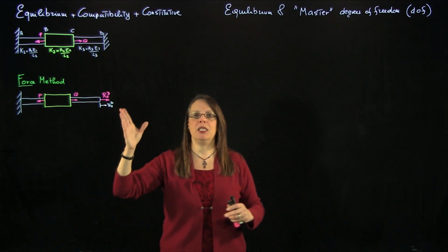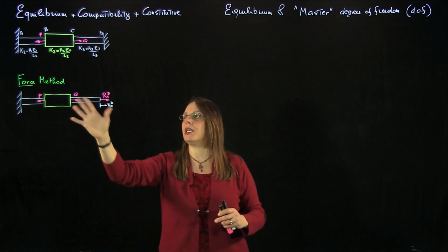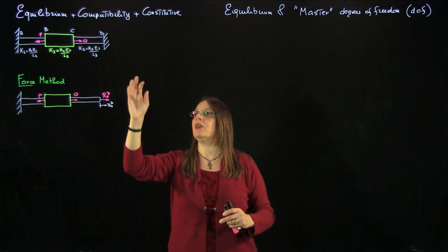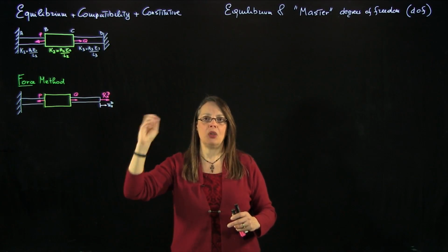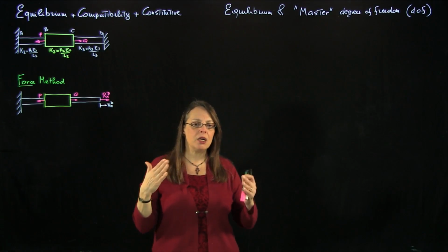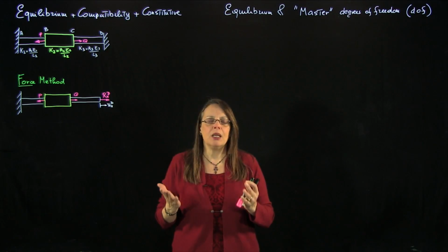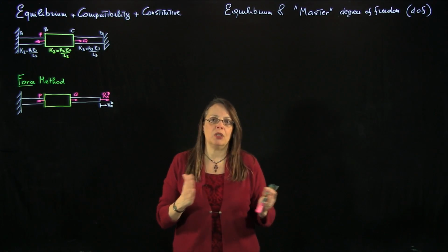But this is typically a decision that you have to make ahead of time if you want to choose something like the force method, because so far we have been using the force method to solve statically indeterminate structures, and you start doing this only once you have recognized that the structure is statically indeterminate. When we start having systems with more bars, more constraints, and so on, sometimes it cannot be obvious to you if the structure is statically determinate or indeterminate.